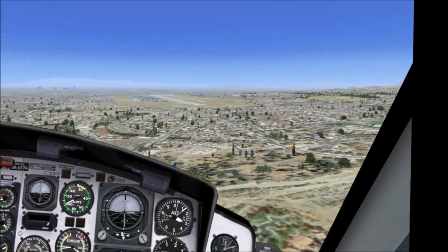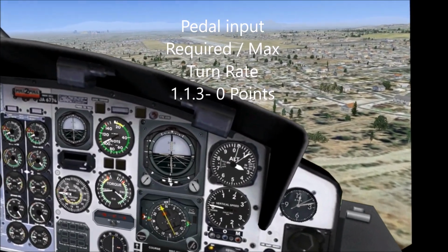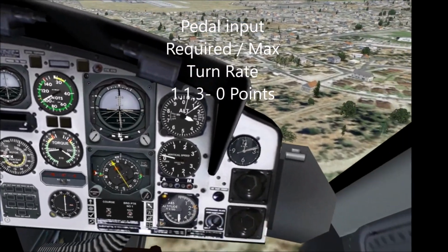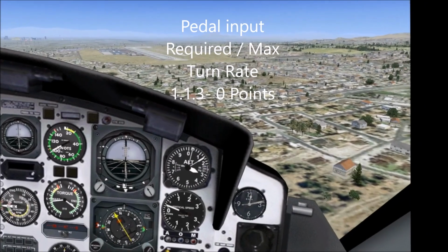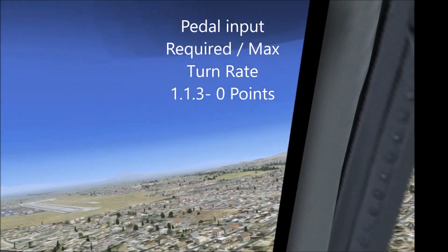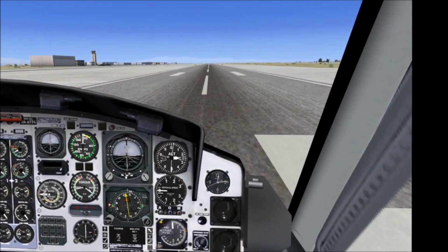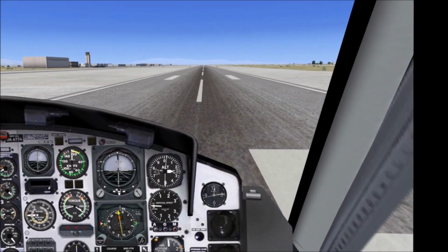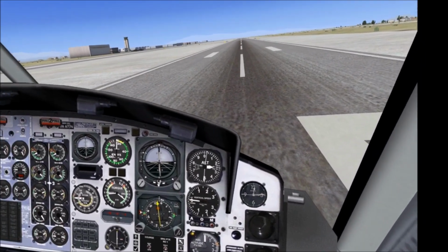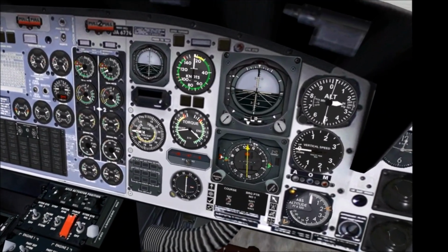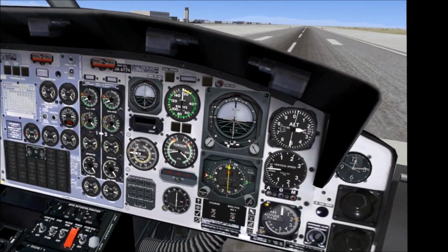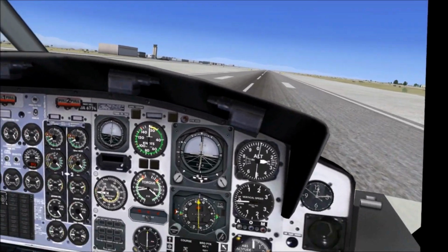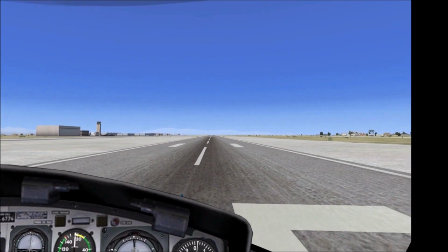With the vertical fin offloading the tail in the slipstream, I would expect a little bit of right pedal in cruise to keep it in trim. So, nah, not too crazy about that. Okay, back at 3.5 left, looking at my torque. So we burned off some gas. So we're hovering right about 25% torque. Oops, sorry.